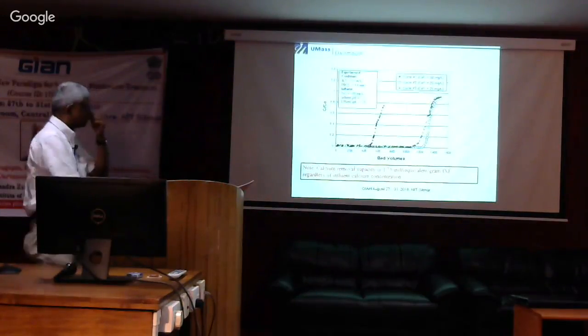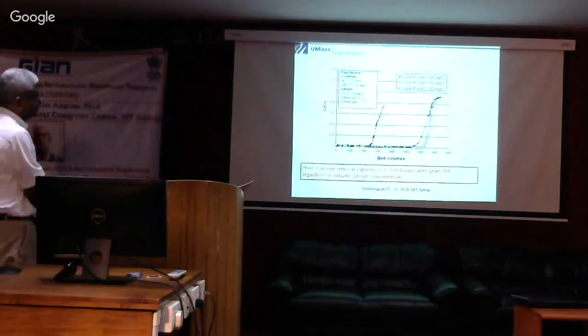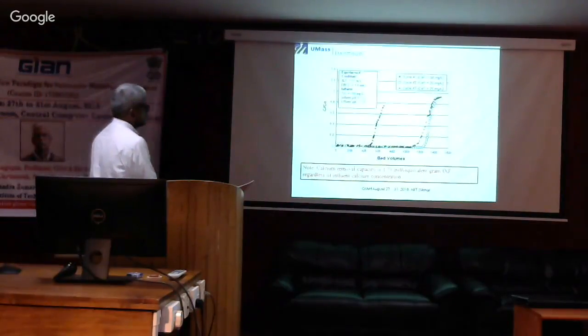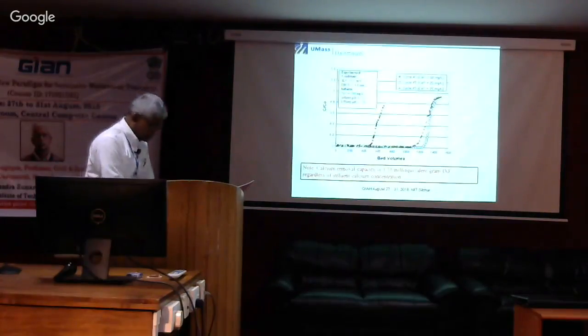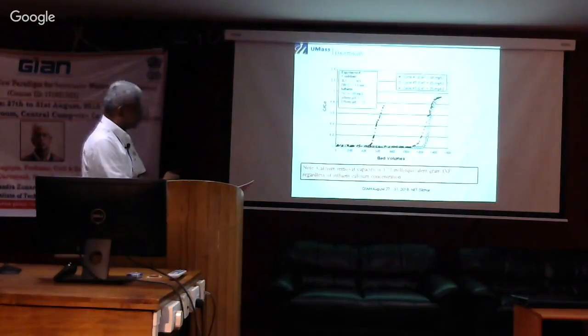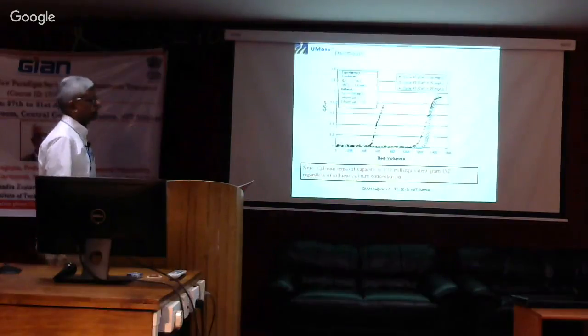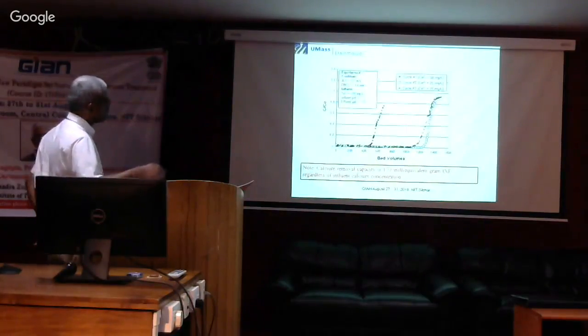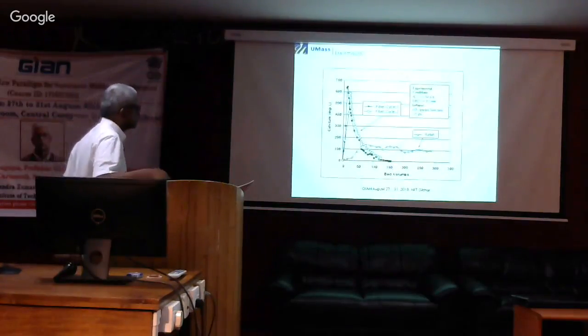And in this case, when we do the mass balance, we found that the calcium removal capacity is 3.75 milliequivalent per gram, regardless of influent calcium concentration. Which is good to know, because if calcium concentration plays a role, then our calculations need to be revised. So this is straightforward classical ion exchange confirmation. Right. So then, how about regeneration?